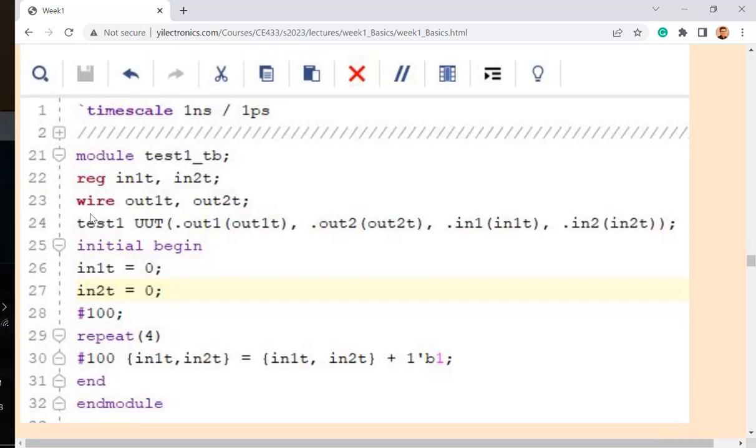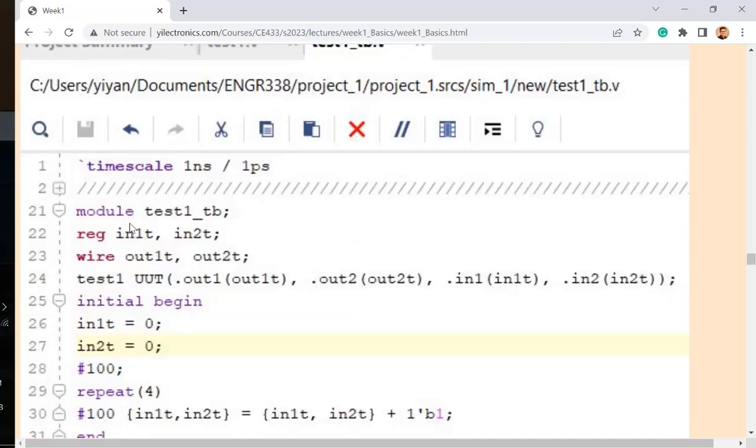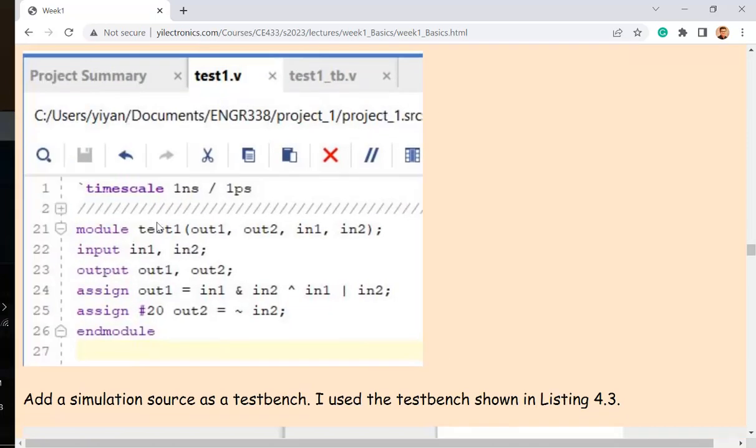And so this one is already included in the test bench. I already formed a test bench. What's the name of the test bench? As the outer layer of the test, right? The test bench, you can imagine, is just the breadboard in the Circuit 1 lab. You grab a breadboard, and that's actually the test bench. And you put your chip, so the chip is the unit under test. I made this module here called test 1, which is a little chip you can grab from the drawer. It has all the ports, right? But it doesn't have any signal on it before I connect anything.